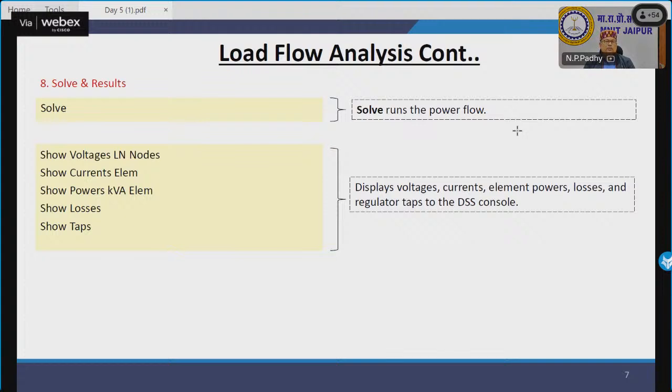Now, first we need to understand what we are looking for. If you are looking for a voltage solution in an islanded microgrid, yes, you can do that. And wind and solar is fine to me, it's not an issue. So you can solve load flow for a small microgrid, which means a small distribution system, but which is islanded. There is no super node or a bus or a grid there. Okay, I think still it is possible. Still it is possible. Yes.